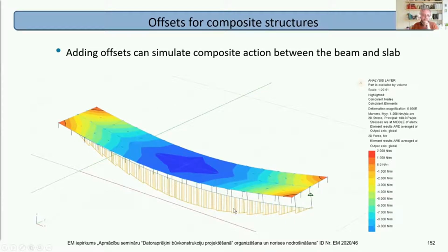One thing to watch out for as well, if you're modeling like this in an FE model, if you're modeling for vibration, then slab continuity is sort of normal good practice. The strains are low, you will get continuity through the concrete slab when it hogs over the supports.